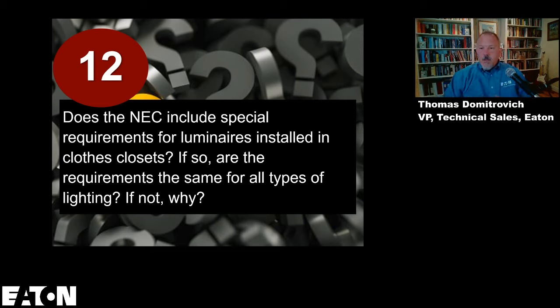Dormitory units not included. Okay, occupancy limitation in dwelling units and guest rooms. So there's a discussion going on out there with regard to dormitory units, 210.6A for 2023. No requirements for AFCIs and 277 volt circuits. That's right. So we're only on 120 volts and 240 volts if you're doing shared neutrals. David Engelhart, so it looks like Brian Rock and David Engelhart are going back and forth. Unit not included, Tom. Should we include dormitory units in 210.6A for 2023?